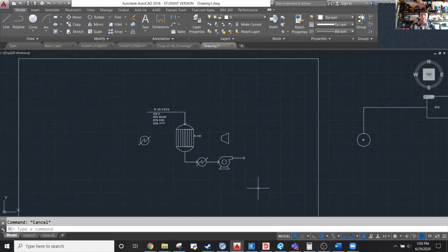Bill covered how to do this in his presentation, but I'll give you a verbal description. It requires a normally open contact in series with a normally closed contact, and then that first normally open contact is going to be in parallel with an output, and that's basically how you're going to latch it.